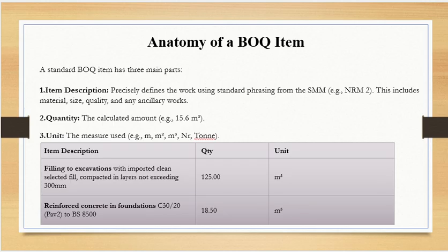So, if you don't mention it, it's part of your contract document. The contractor will see, okay, no layers mentioned. So I can fill however I want. I don't need to do compaction. I'll do the full 1 meter and do the compaction once. Okay, you can do that. You did not mention. Got it?